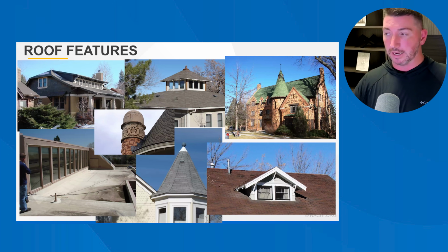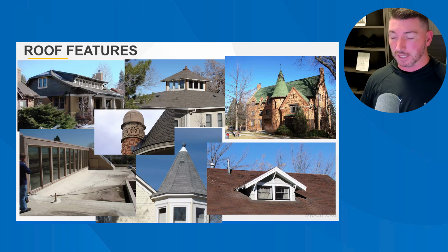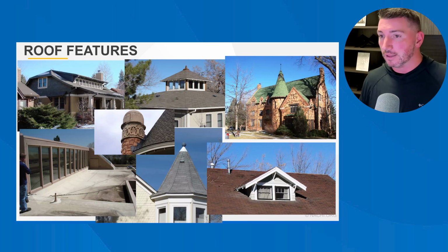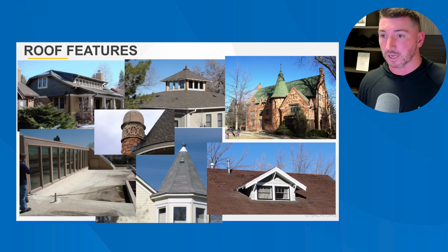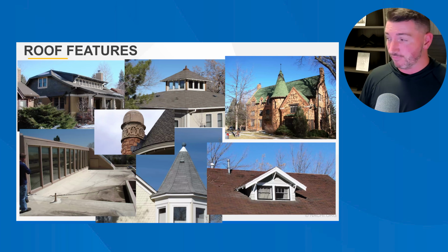So what they're saying here is that there's so often an issue behind a conical roof that if you physically can't see in any way, whether with binoculars, whether with the ladder at the roof eave, if you can't see behind that conical roof, then you really should recommend that a qualified professional go look at it. I like to get on all the roofs that I go to, so I'll usually see behind that. But the use of a drone is also very good for seeing areas like that and getting up close.